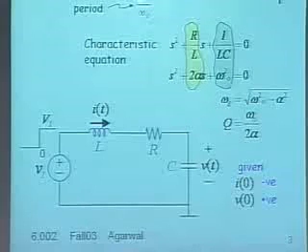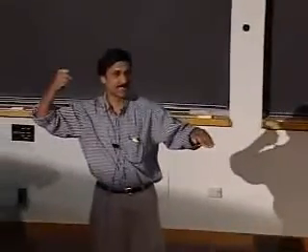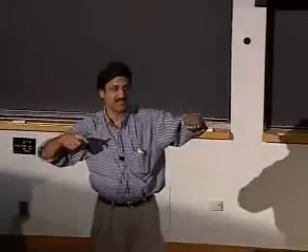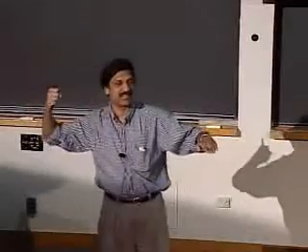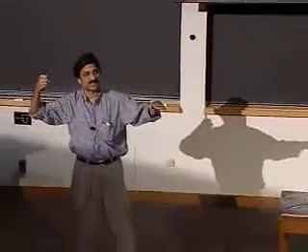It's trying to hold its current, and its initial current I0 is in this direction. So the capacitor has a voltage V0, and the inductor is yanking the current in that direction. So what happens to the capacitor? What should happen to the capacitor voltage initially? If I'm at V0, and someone is yanking current out, at least initially in that direction, what should the initial dynamics of the capacitor voltage look like?